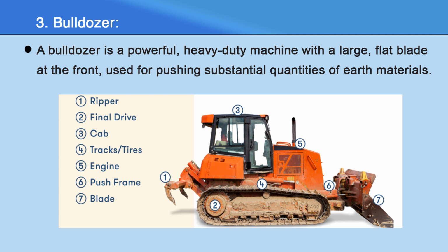Second, based on mounting. Now, wheel-mounted bulldozers are ideal for long travel distances and handling loose soils, offering a fast return speed. Crawler-mounted bulldozers, on the other hand, excel in short work distances and handling tight soils. They have a slower return speed.